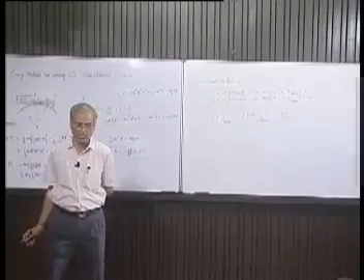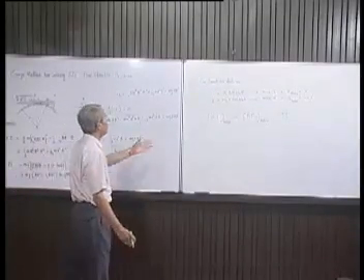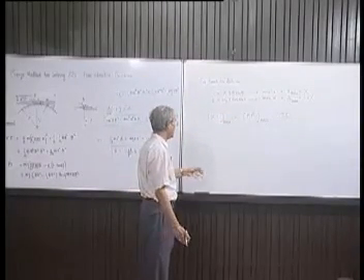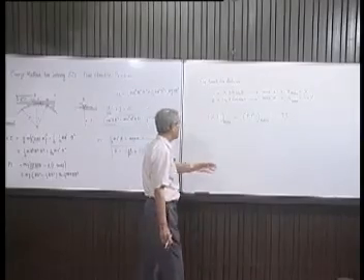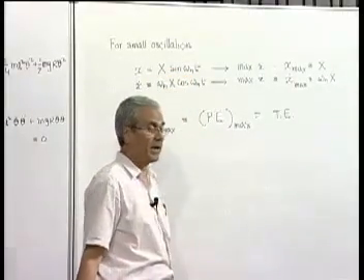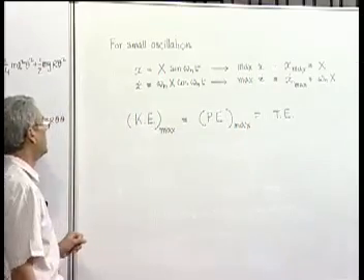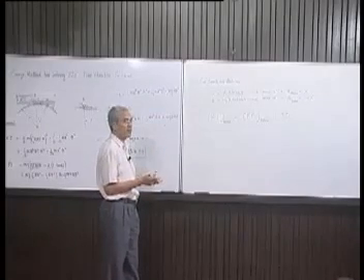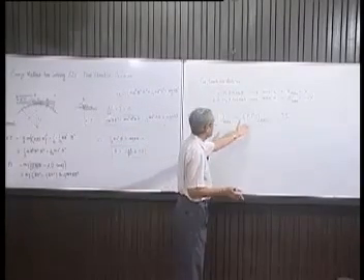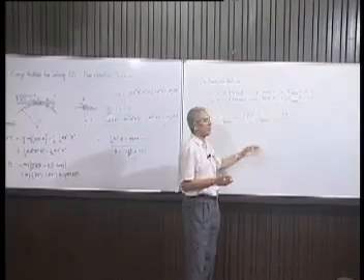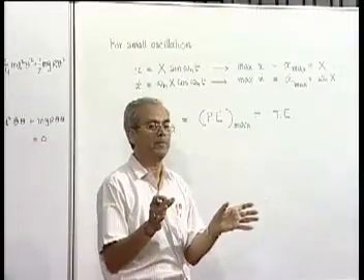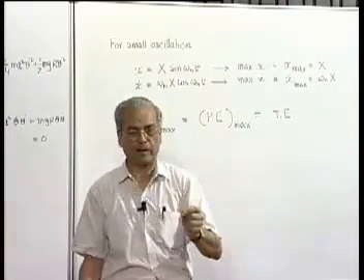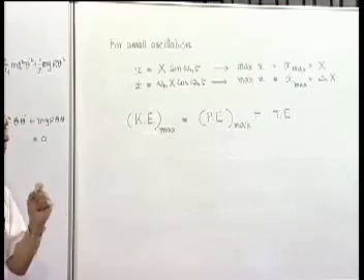So now what we can do is take this approach: we know that for all small oscillations, the oscillation is going to be simple harmonic. The only thing that is unknown, and we have to find out, is the natural frequency omega n. So what we will do now is find the expression of kinetic energy in the system and its maximum value, find the expression for the potential energy of the system and its maximum value, and equate them. Since the kinetic energy term contains omega n, we will get an equation in omega n, and that way we can find the value of omega n.